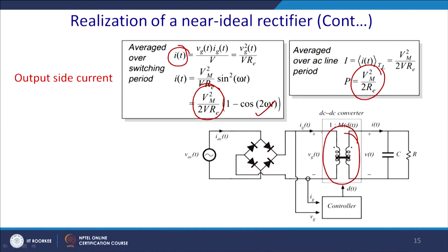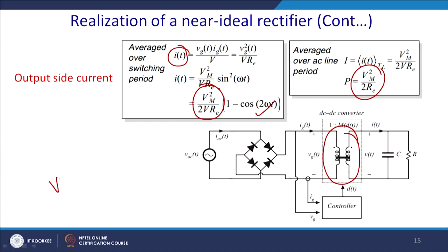Of course, you will have a lot of merits to use it, and the beauty of it is a high frequency transformer, since it is very high frequency. Generally, you know the expression of the voltage, if you assume this part is sinusoidal, it is 4.44 BANf. So, if you increase the value of f quite high, then this part is essentially the geometry of the core.